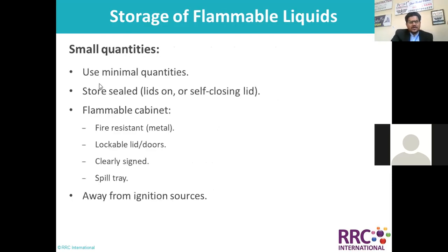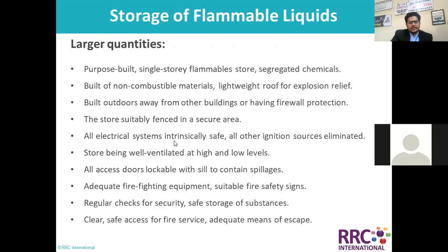If you have small quantities, use minimal quantities, stored with a sealed, self-closing lid in a flammable cabinet: fire-resistant metal, lockable, clearly signed, and also with a spill tray, away from ignition sources.